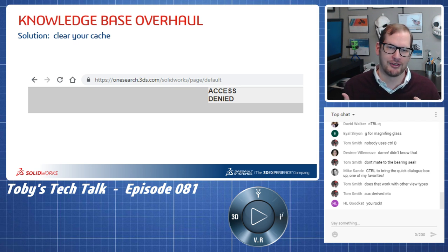I love the SolidWorks knowledge base. I'm always in there looking for answers, and it's a great way to quickly get your answers resolved. So when I first ran into this, I was like, oh no, and then I was like, well, first thing you always want to try if you ever run into a weird case like this, first thing you can try is just to clear your browser cache, or maybe try it from a different computer that hasn't run it before. That'll validate that the browser cache could be the issue.